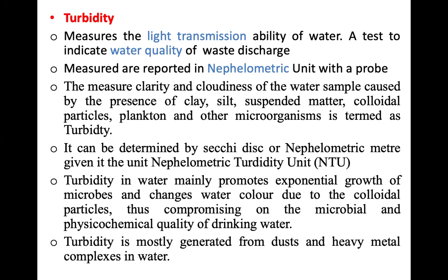Ordinarily, water that is fit for drinking must not exceed 5 nephelometric turbidity units, that is NTU 5. But these days, because of climate activities, some water bodies are polluted with turbidity of more than 14,000, 15,000 nephelometric turbidity units, and this makes it very difficult for treatment. And as they occur, they also affect aquatic life, and the water is not fit for drinking.